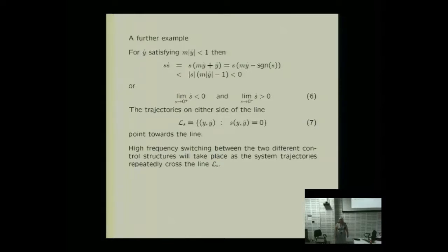which let us develop the size of that control to be big enough so that first stage of the motion is minimized. And if you look at the literature, and if you look at different academics, different people, you will see numerous different conditions. There are lots of conditions. They're typically called reaching conditions, reachability conditions. And it's a condition to try and pick a control, fundamentally, choose a control U that lets you reach that dynamics S that you've picked. Okay? So it's about choosing the control to make the dynamics attractive.